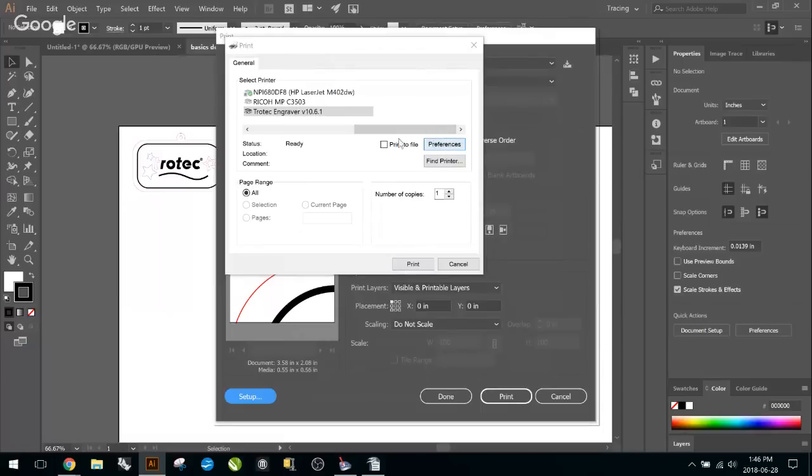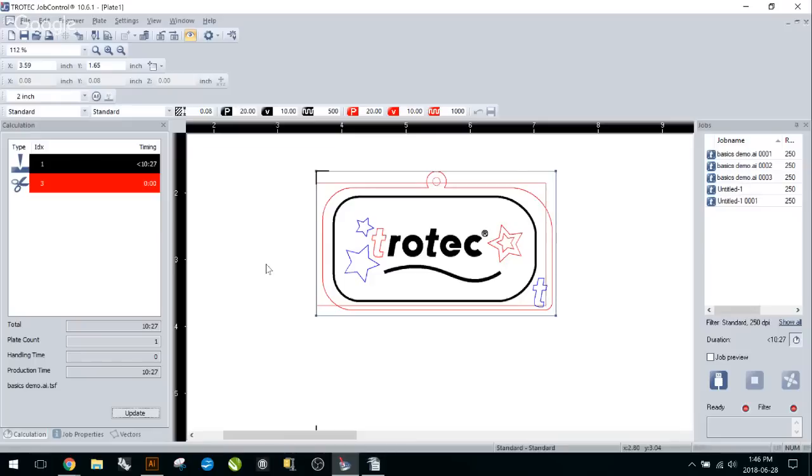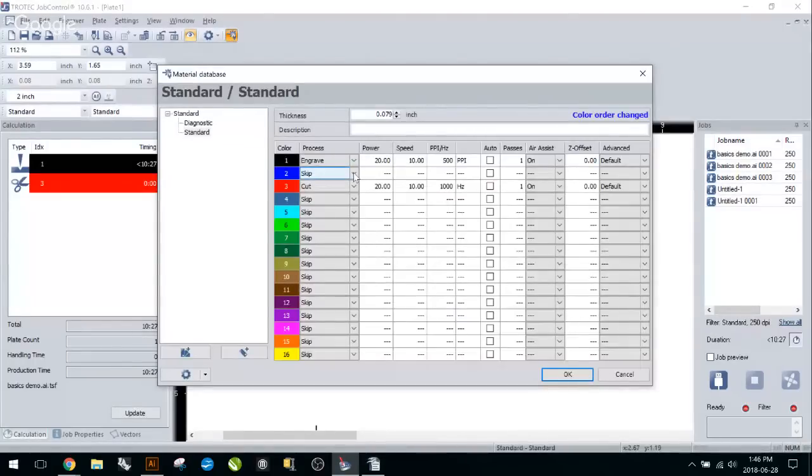So we'll go back in there. Somebody just asked, is kiss cut and engraving the same thing? No, because engraving, essentially, if you go into job control, Anthony, and then go into the colors. So when you're putting the setting, if you click on the black engrave, yeah, see how you only have engrave, cut, skip positioning. Positioning is for the vision camera system, but, or sorry, it'll have reg marks if you're using the vision camera system, but essentially you have engrave and cut options. So kiss cutting, it will be under cutting. If you want to click on the cut, so we'll just show you the difference.